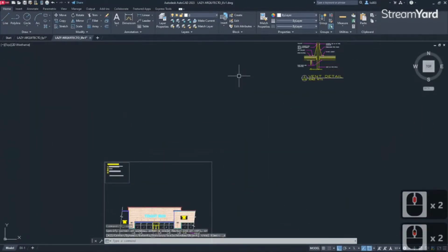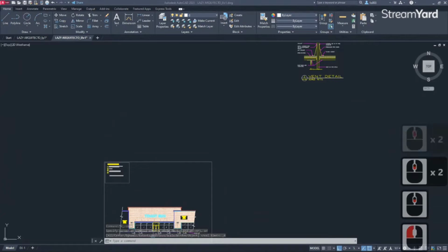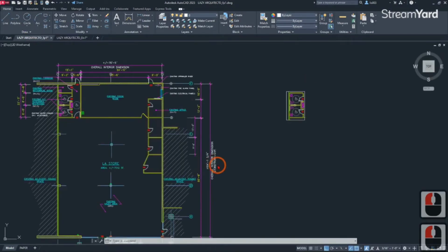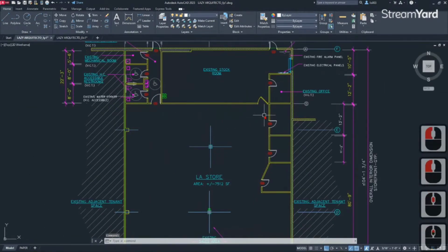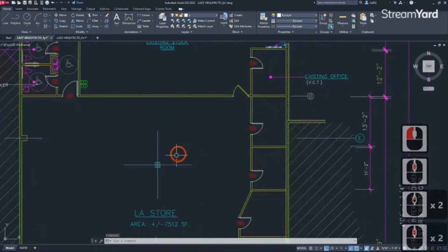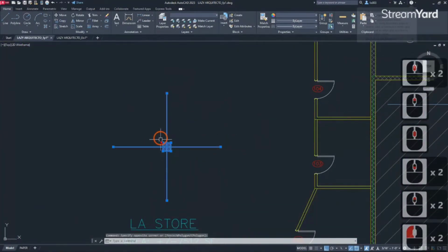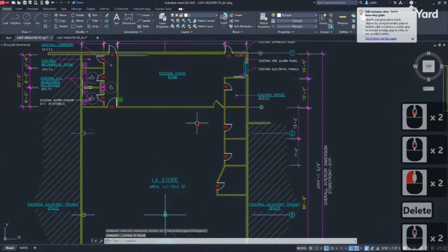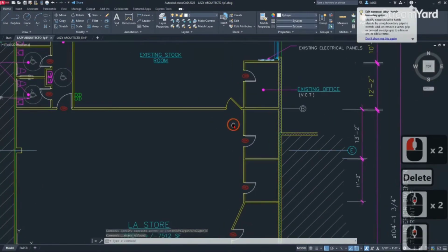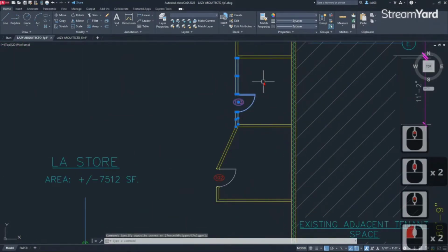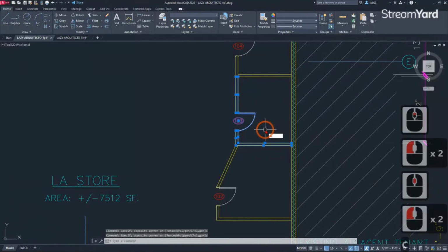And this would be the oops command. Yes, so sometimes it happens that you are working on a drawing, and let's say you're working here in this drawing and by accident you erased a column, just to give you an example, and then you keep moving over here, drawing rooms and so on.